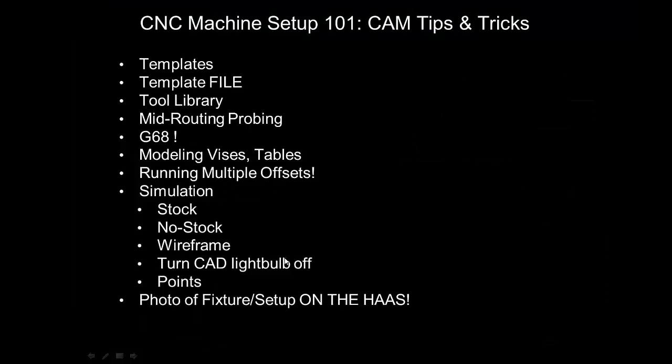And okay, really the last thing, I haven't figured this out, but I figured if I put it in here, it'd be a good impetus to go figure it out. Apparently on the Haas, I can take a picture with my iPhone of a setup on the machine, and I can somehow store it in that job or file or something, which is incredible, because what that means is in 3 weeks when I go to rerun a job, I load my CAM, and then I can literally open up a photo on the Haas controller. I hope I'm not wrong on this. I'm pretty sure I'm not wrong. And it'll show me the orientation of the soft jaws or the fixture or which ones I was using. That to me is such a breath of fresh air for being lean and how I stay organized and make good parts. So I'm going to stop rambling there, but happy to answer questions.